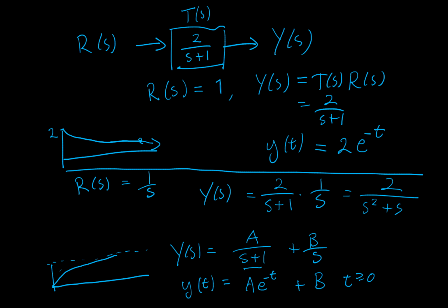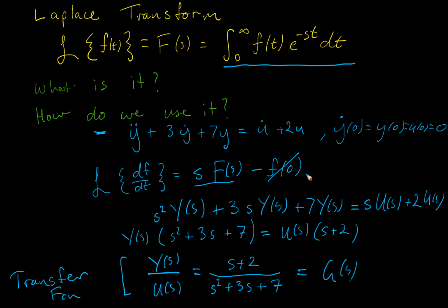So hopefully that's cleared up a little bit, at least the way that we use Laplace transforms. What you'll see is that throughout all of this, I never actually even looked at this integral. I never tried to compute any integrals like this by hand, and that's typically the way things work. When we're dealing with Laplace transforms and transfer functions, we're never really dealing with this integral. We're just dealing with manipulations, products, and so on of polynomials and rational functions.